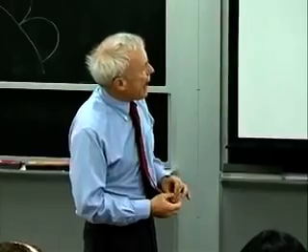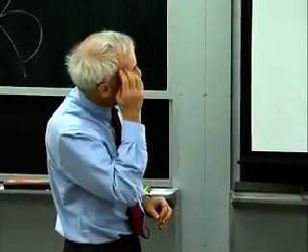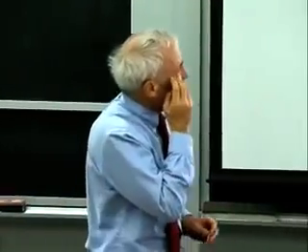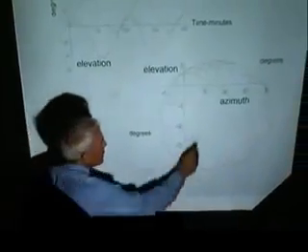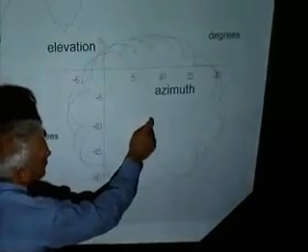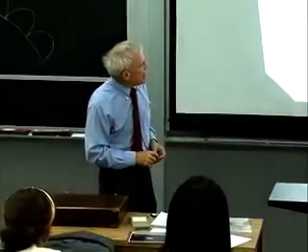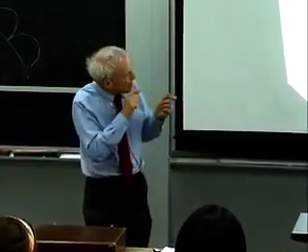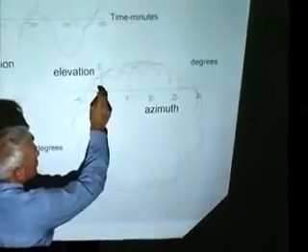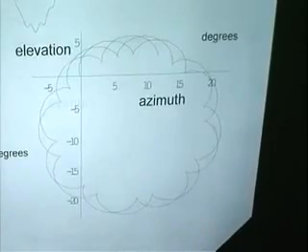What's next? And that's when I had the insight that the problem was that the angular momentum vector from that initial condition was somewhere off here, 10 degrees or so away from that initial angular velocity. And if we wanted to have a more constrained motion with the jets turned off, then we had to somehow get that angular momentum vector initialized much closer to the direction that we wanted to point.